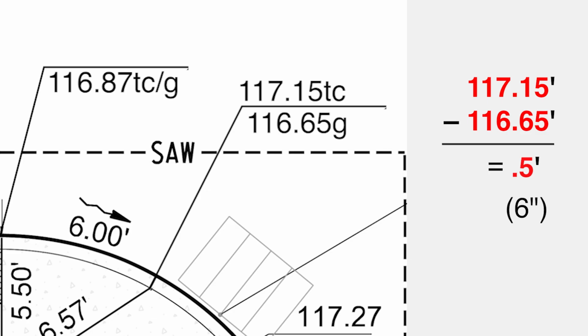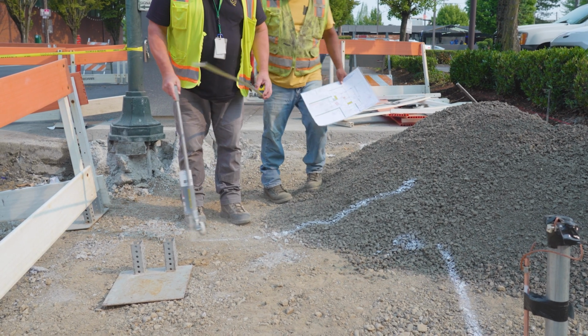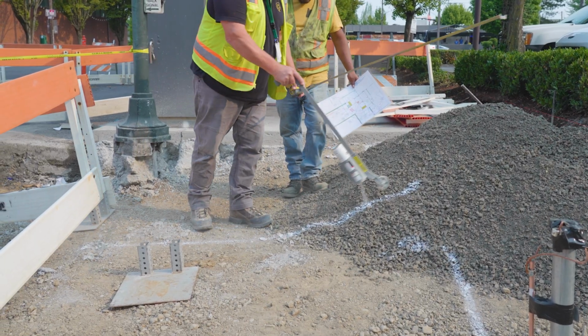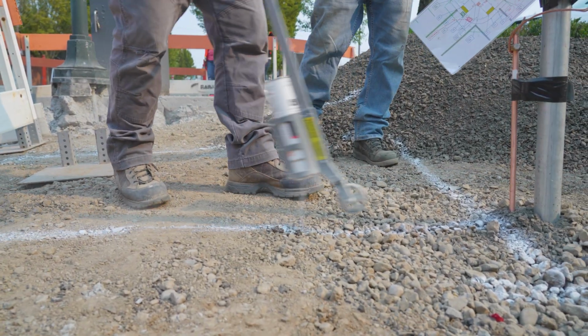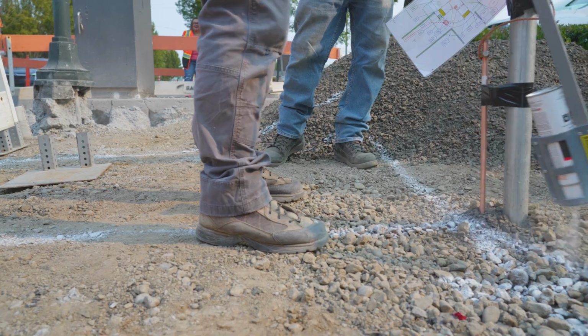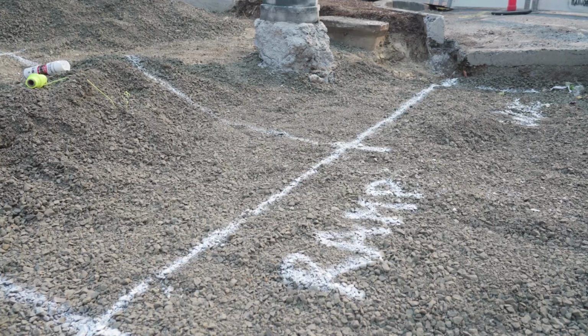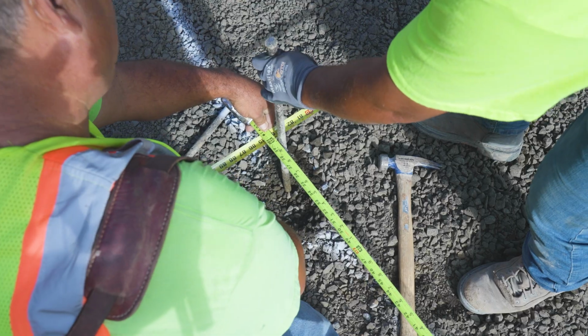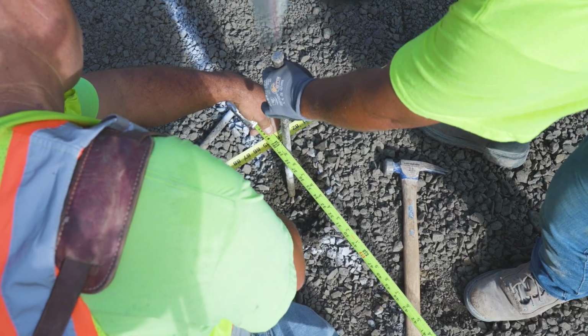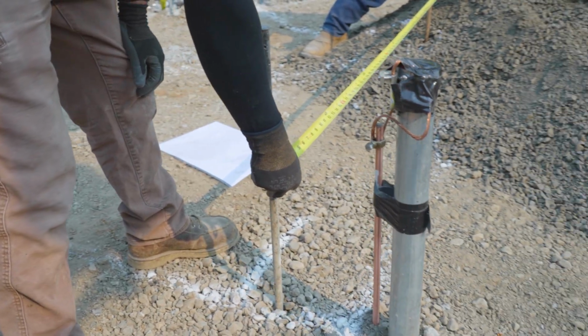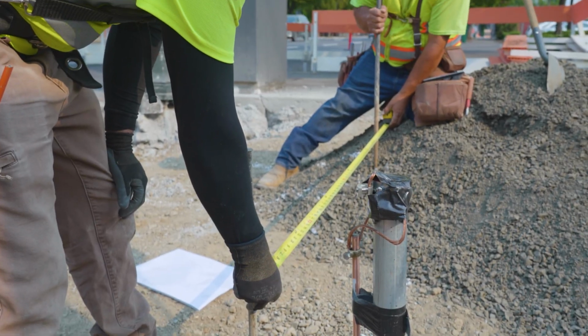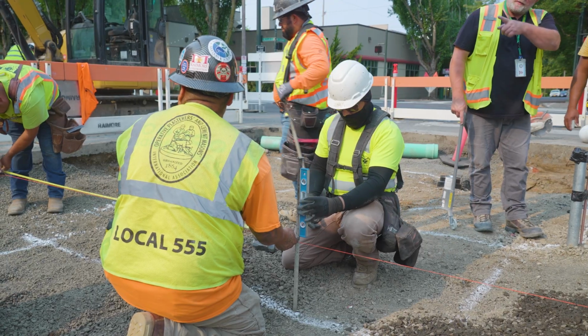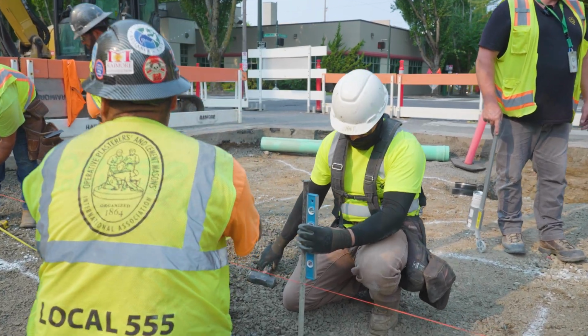Math may not always be fun, but it sure makes everything clearer. Questions answered. Use your plans to start spraying out the panels so everyone knows what's where. Then, staking at panel intersections. Double check those placements frequently, since stakes can and do shift or tilt. And use a bubble level to ensure every stake is absolutely vertical.